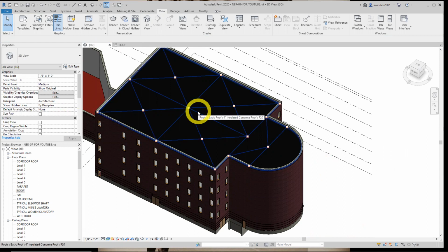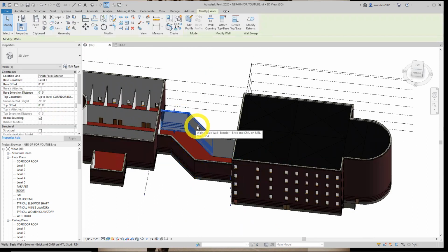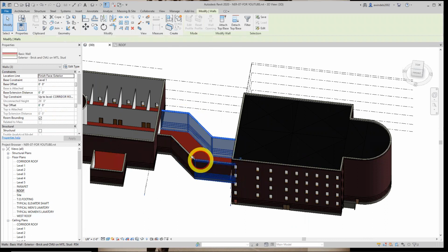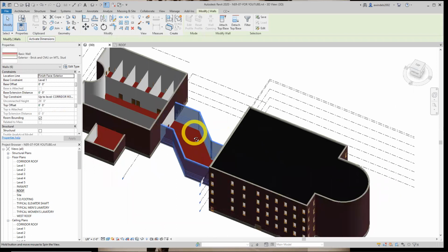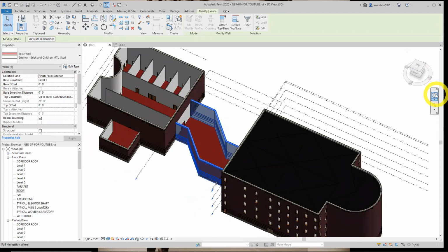We're going to start with the corridor. We're going to do some pitch roofs in the corridor area now. Let's start by selecting all 6. I'm using Control, left click to hold them, Shift and middle mouse to orbit around if you need to. That's one way I like to do it. There's also this command within the orbit wheel and your view cube, of course.